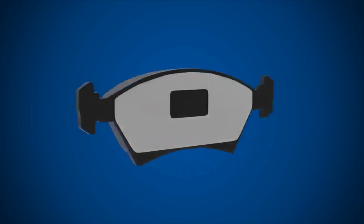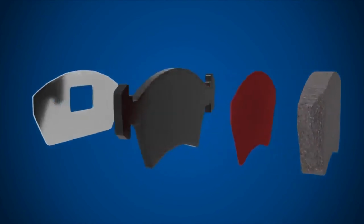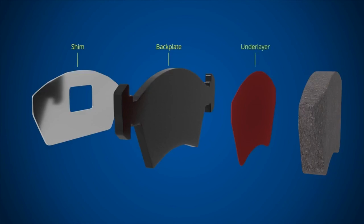Brake pads squeeze against the brake disc and produce the friction required to slow the vehicle. At the back of the brake pad there is a shim, which is designed to reduce vibration and noise. Next, we have the steel backplate, which provides the rigid base for the friction material and solid mounting to the caliper piston and carrier. An underlayer, sandwiched between the backplate and friction material, bonds the two together and acts as a thermal barrier to stop heat being transferred from the pad to the caliper.